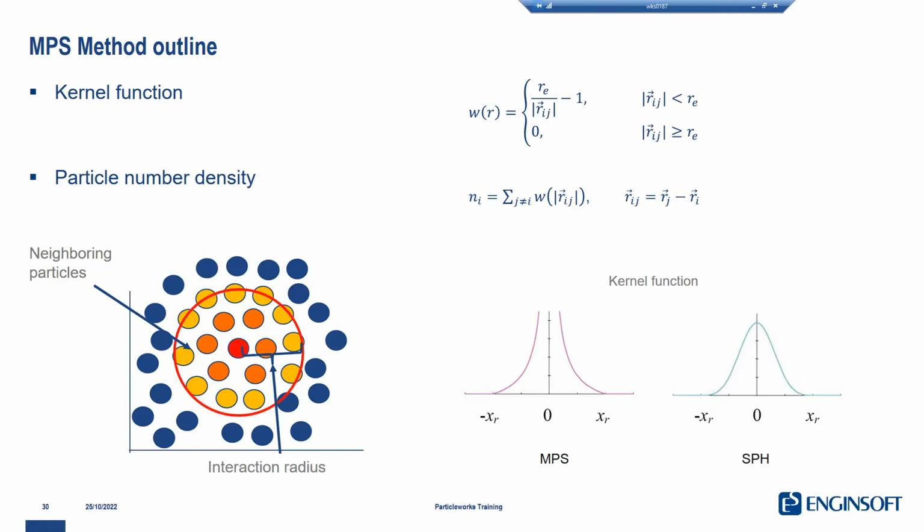Basically yes. Not every time step, but every saved output, because you have an intrinsically transient simulation here. You don't have residuals. You will save maybe every 1 millisecond. You have a result, okay? For every result, you can monitor some stability aspects like the number density, average number density. You can have a look at the results themselves and understand if they are reasonable or not in terms of flow. In most cases, you see explosions, you see non-physical behaviors, you see particles maybe going through the walls. All of them are indications of unstable results, okay?